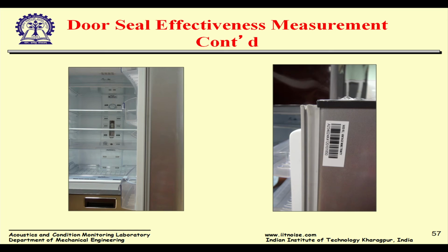So you know how effective this seal is, because we talked about the flanking path. You have a nice thick shell, and the shell has good transmission loss, but you have very poor seals at the doors, and that is true in many of the applications which I have seen. We will see how the seals could be improved to reduce the noise, be it an automobile, a locomotive, or an appliance like a refrigerator and so on.